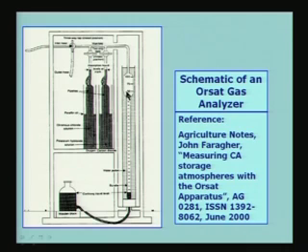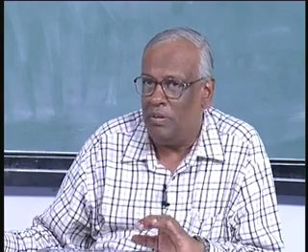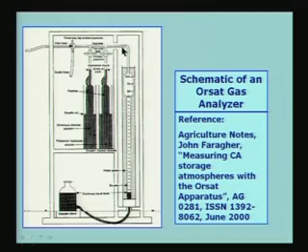The third point I would like to say is that because the liquid contained here is water, the entire manifold here and the burette and so on will be fully saturated with water vapor, because there is enough water available for that, and therefore, the measurement is on what is called dry basis, because we are not taking into account the moisture which is always present. So, even if moisture is present in the incoming gas sample which we are going to measure, the water concentration is not going to affect the measurement, and therefore, we call the measurement dry basis.